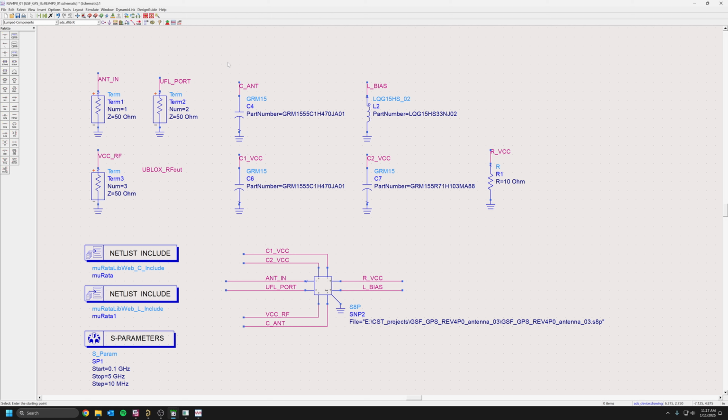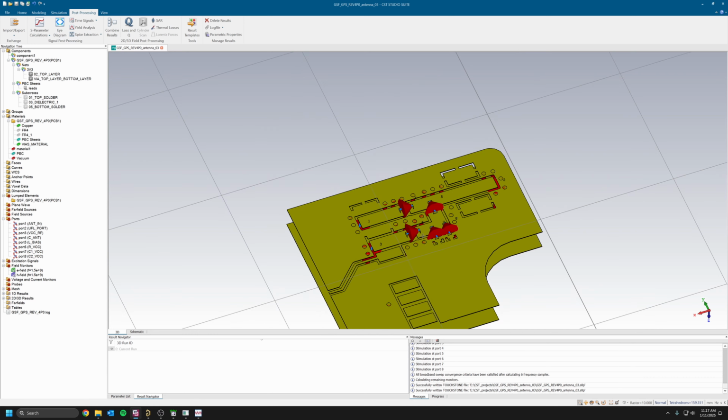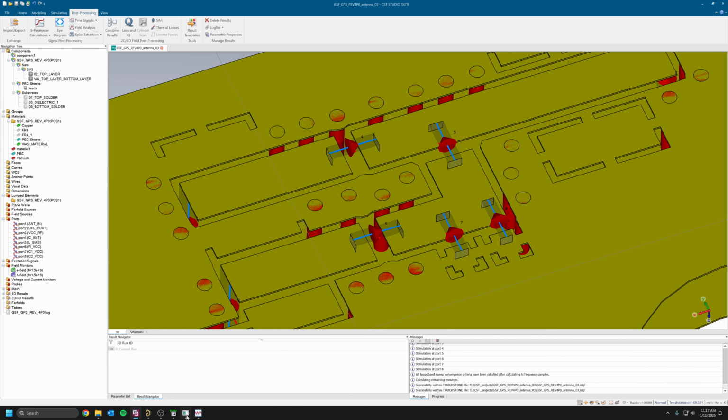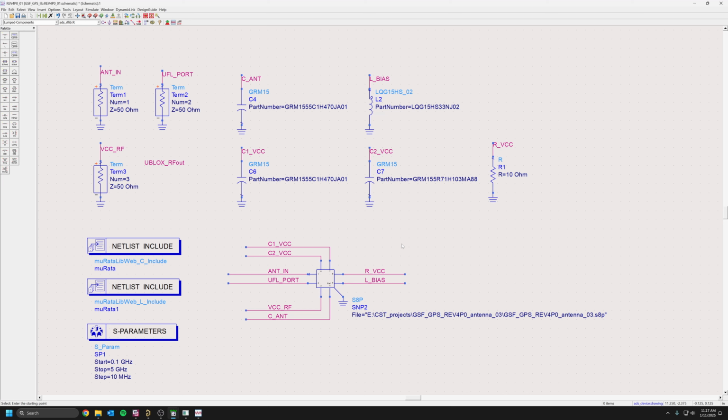I won't explain in this video why I set up my ports to a component and then to ground to mimic the connections that I made here. Just know that that's how I did it, and I can explain it in some future video. Basically, I want these components: a 47 picofarad capacitor for my series capacitor, and my inductor is 33 nanohenry.